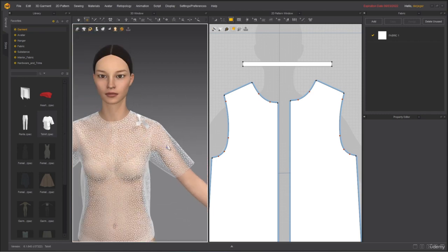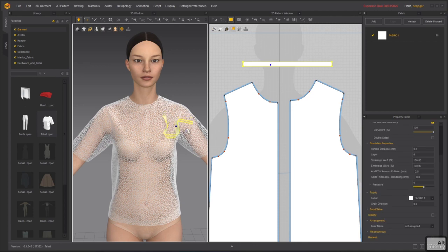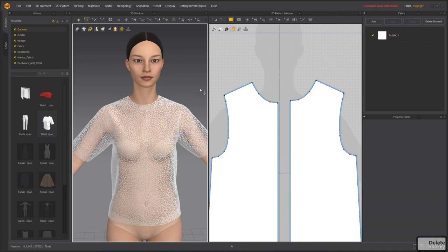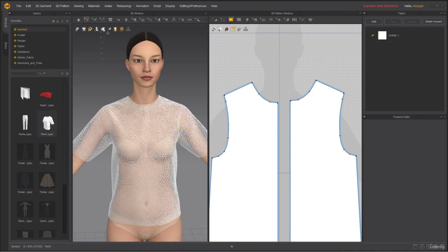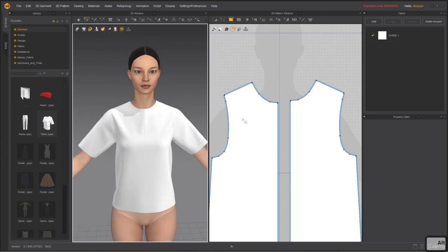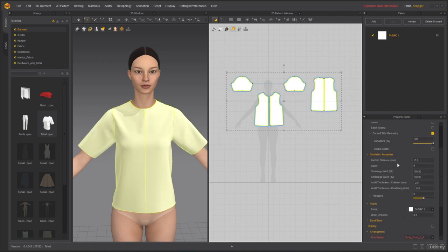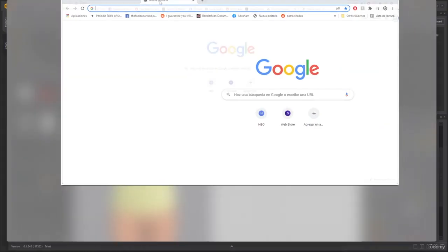Otherwise, just lower the particle distance at the very end of the garment production so that things flow in a better way. Okay? Now, other than that, there's a couple of things that fabrics have, all patterns have. Here, let's go texture, that are going to dictate how they simulate. So if I select everything right here, you can see that other than the particle distance, we also have this thing called shrinkage weft and shrinkage warp. This has to do a little bit with cloth.